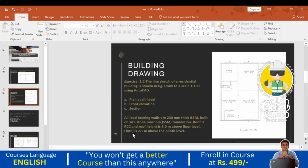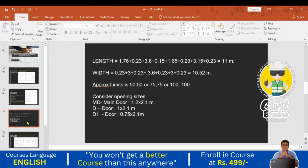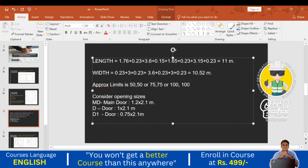So here, what is the height of the level, here the floor level, lintel is 2.1 meter from the plinth level, it is already given. So that's why the height we are considering is 2.1 meter. And as per the standard and whatever the construction practice is going on in the field, the lintel height is 2.1 meter only. In most residential buildings, we are considering 2.1 meter height of the lintel only.